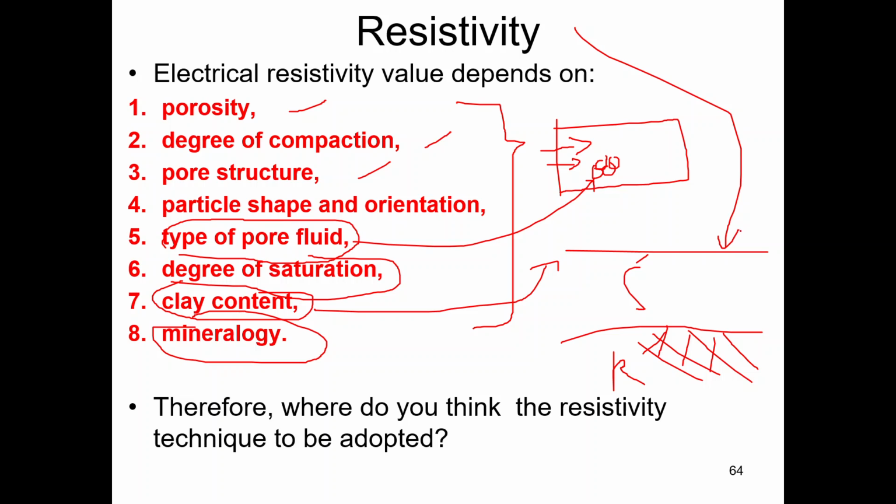Is it possible? Sometimes possible, sometimes not possible, because of water. If we have a very low groundwater table, see our water table here, then all this material is submerged underwater. And let's say we have a very fractured rock, and the fractures are filled by water, then just imagine all this material is saturated.